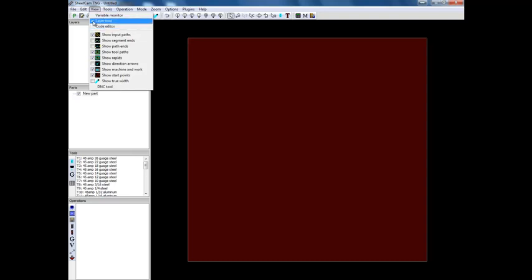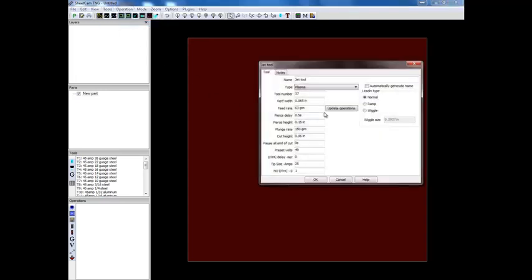Now at this point we are not done. The first thing we need to do up here is go to view. You're going to make sure that your layer tool is selected here. That will give you your box here that will show you your layers. Next you go to tools and you select new jet cutting tool. Now on your screen when you do this, this box will be checked here. You're going to make sure you uncheck it and then click OK. That needs to be done prior to installing the tool set, otherwise the tool set names will be incorrect and much harder to decipher.